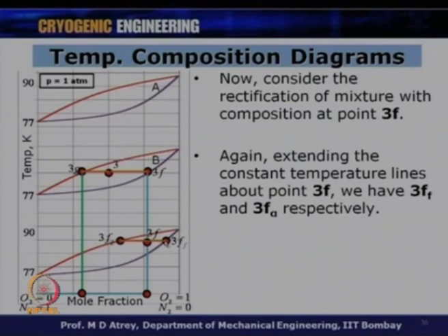What I will do further is take this composition, and the liquid plus vapor at this composition will enter this diagram again, so that I am going towards the right side. My rightmost point is nothing but oxygen equal to 100%, that is 100% high boiling component. The objective of repeating this process and entering the same curve again is basically to reach the rightmost point, which is 100% oxygen. That means my liquid is getting richer and richer in the high boiling component. All right.